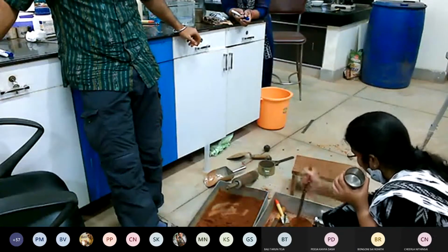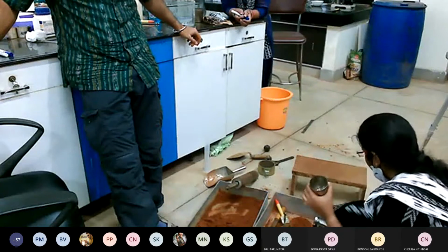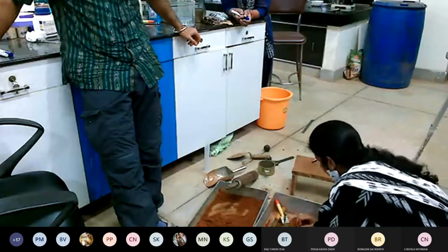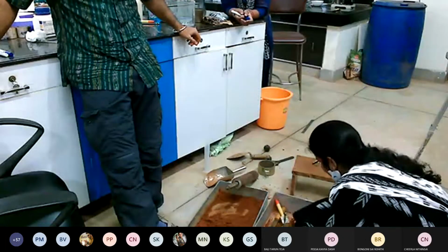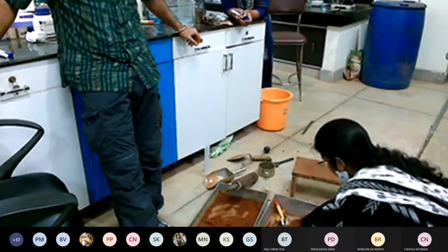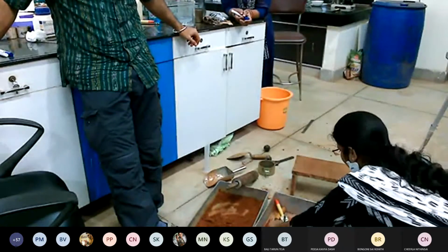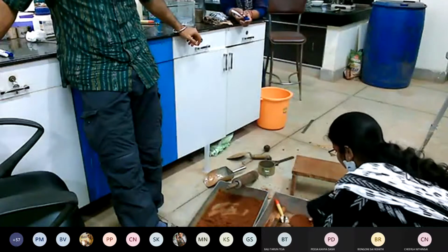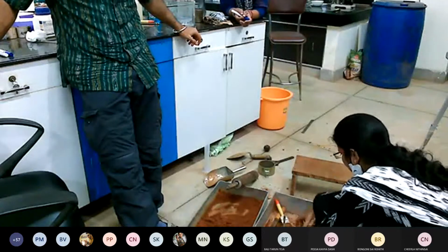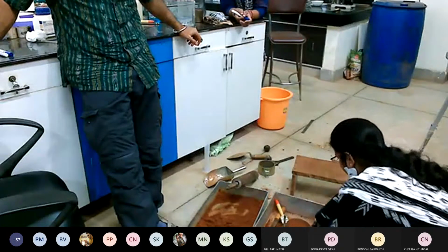When we are actually conducting the moisture content, standard Proctor experiment for a soil, we'll keep on doing this till the weight starts decreasing. And once you get a decreased weight, you need to take at least one more reading after that to form the curve with free hand.